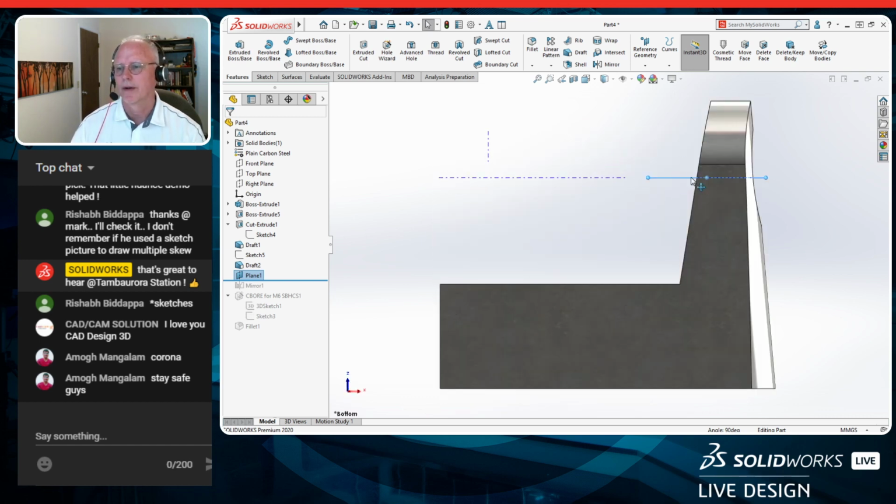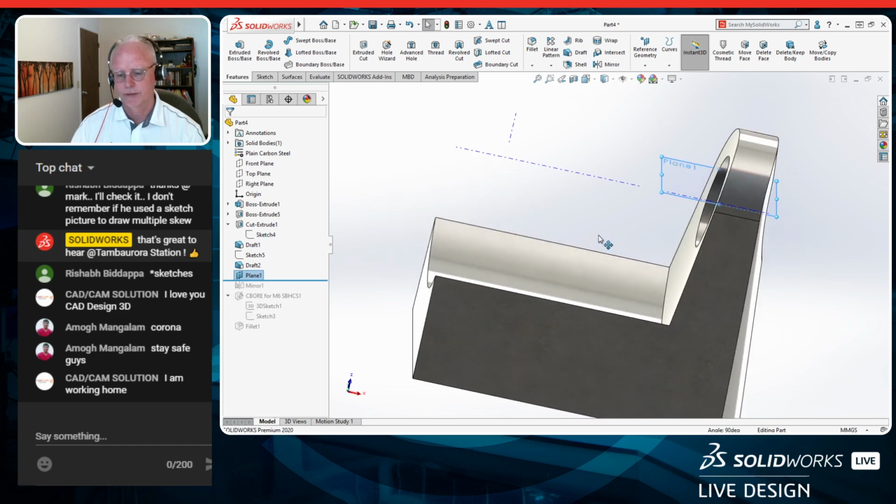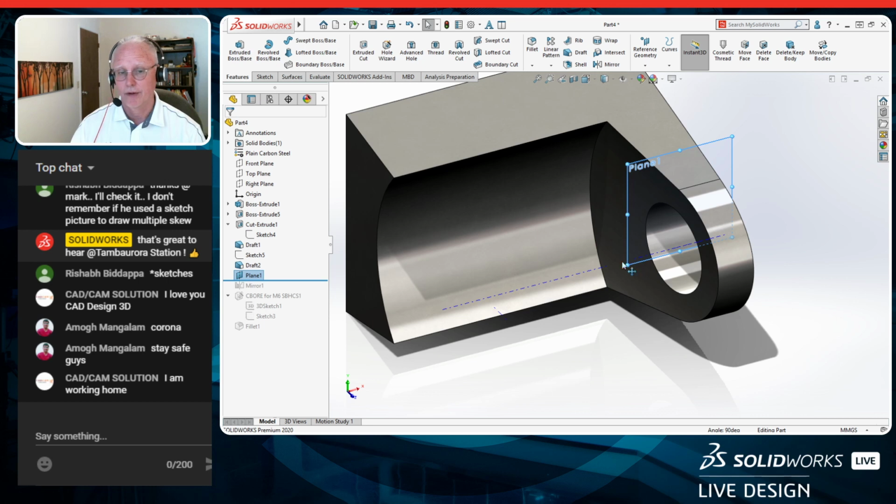Jump to a bottom view here. Through that axis, that's my axis there. Everything looks just as I want, and we're going to use that as our neutral plane for our draft. Actually, I move my draft down here. That's fine. Just do a reorder.